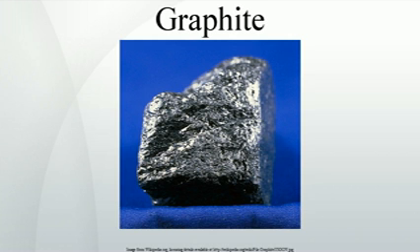There are two ways of obtaining a commercial concentrate or product: repeated regrinding and floating, up to 7 times, to purify the concentrate, or by acid leaching, dissolving the gangue with hydrofluoric acid, for a silicate gangue, or hydrochloric acid, for a carbonate gangue. In milling, the incoming graphite products and concentrates can be ground before being classified, sized or screened, with the coarser flake size fractions, below 8 mesh, 8 to 20 mesh, 20 to 50 mesh, carefully preserved, and then the carbon contents are determined.